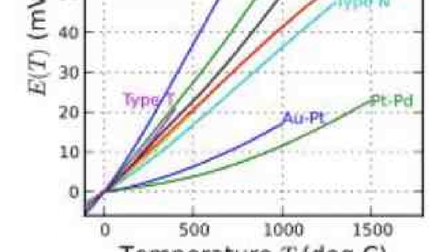The next is the T type thermocouple. This temperature range is very low, for low temperature ranges, but it can cover negative ranges also. We have discussed it, -50 to 400 approximate degrees centigrade. That's why we can use this for negative temperatures. That's the beauty of the T type.